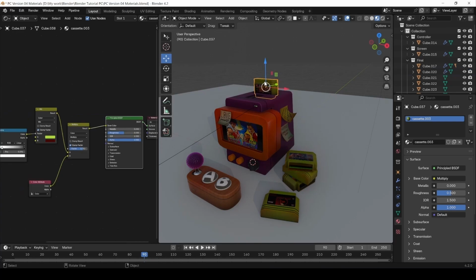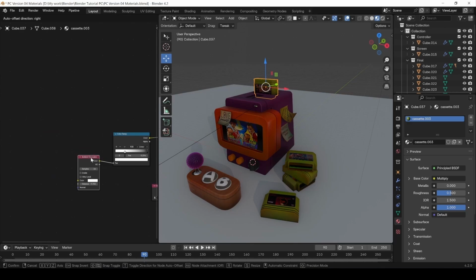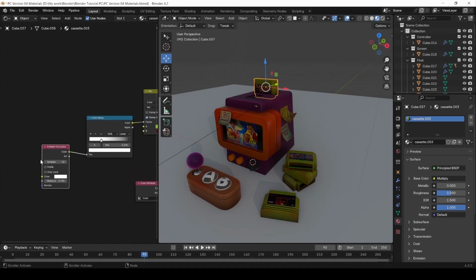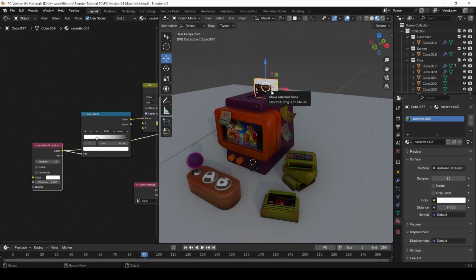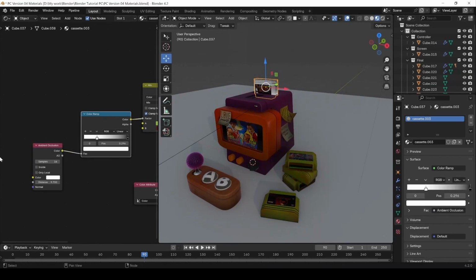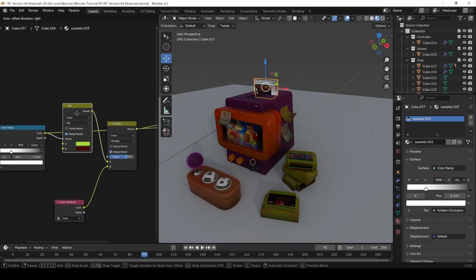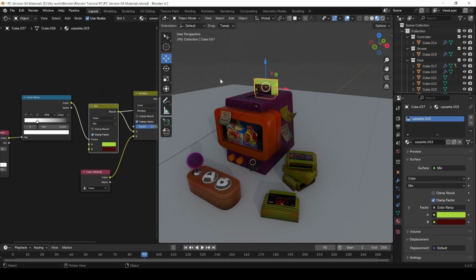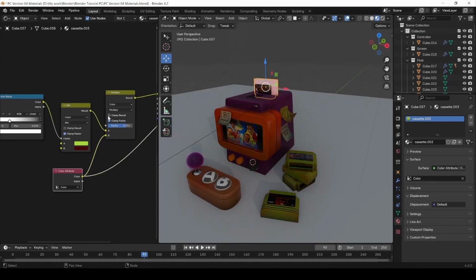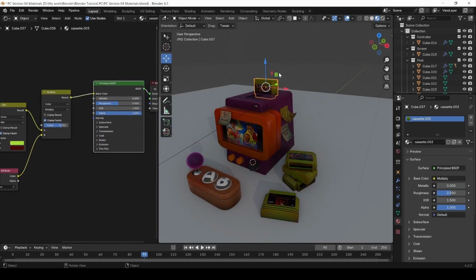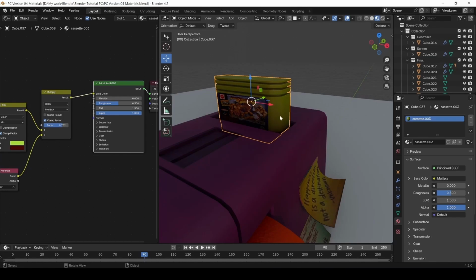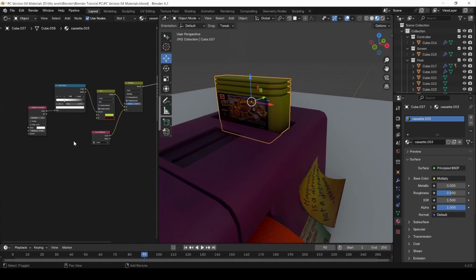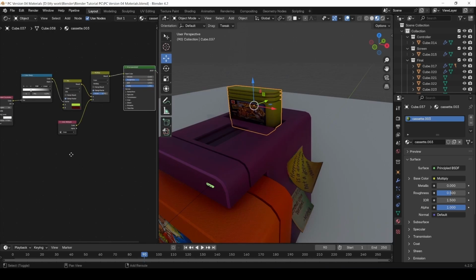Okay, so what we did is that first I created an ambient occlusion. As you can see, it is how it looks. Then with this is how it looks. We controlled it with a color ramp. Then we linked the color ramp to a factor and mixed it between this color, which has these values of green, and this brownish color, which has these values, to give it this speckle. And then using this, we did a lot of coloring to give it that yellowish color around it. There are of course other ways to do it, but this is how we did it here.